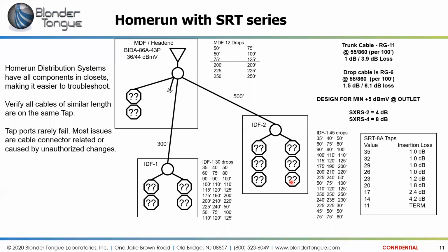Can you damage an amplifier if it's running not connected at full output? Short answer, yes, because it's running into an open and reflecting right back on itself. I mean running at full output, but without a load. That's essentially what I just said, yes. If it's running full output with no load connected to it, it's running into an open and reflecting right back on itself. I will verify with the engineers tomorrow, but I'm pretty sure that's going to cause issues with the amplifier.